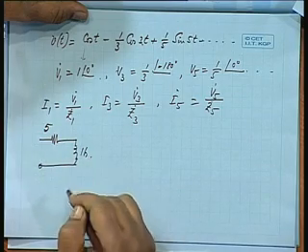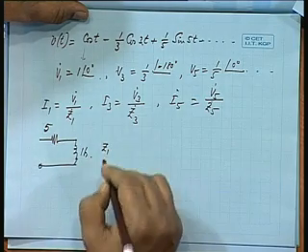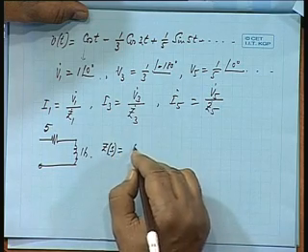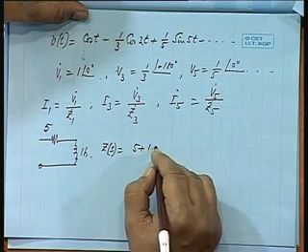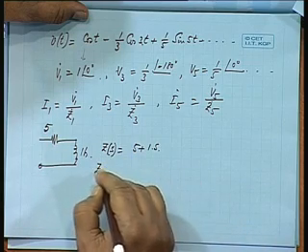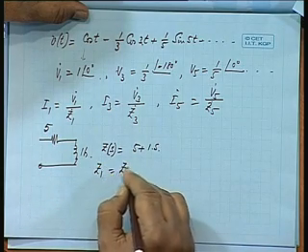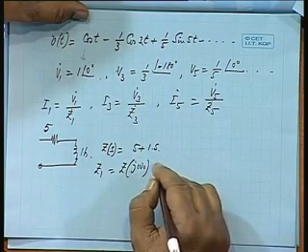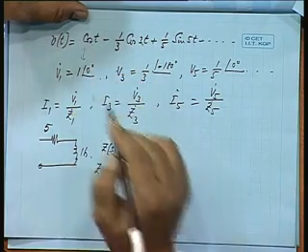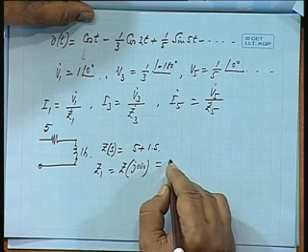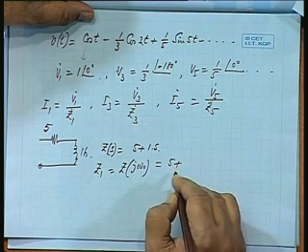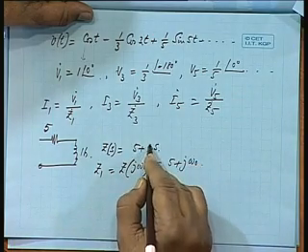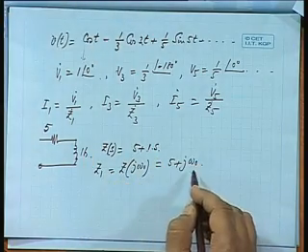So, in this case, suppose we have a resistance of 5 ohms and an inductance of 1 Henry. So Z(s) will be 5 plus 1 into s. Z1 will be Z at j omega naught, where omega naught is 1, cos 1 into t.